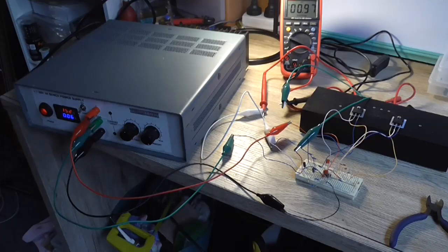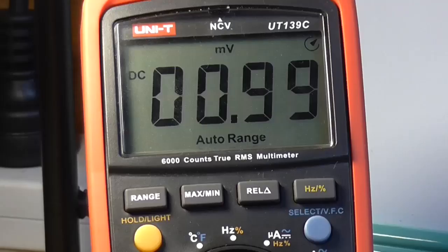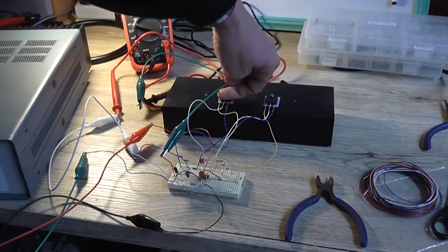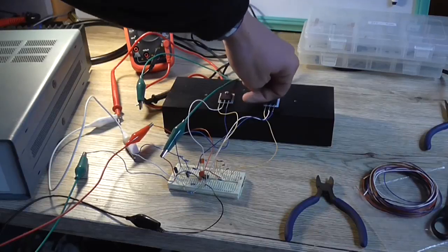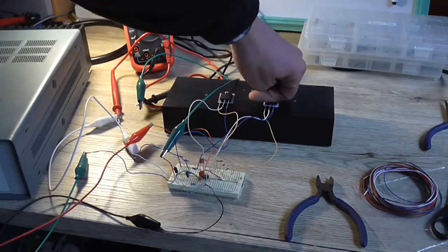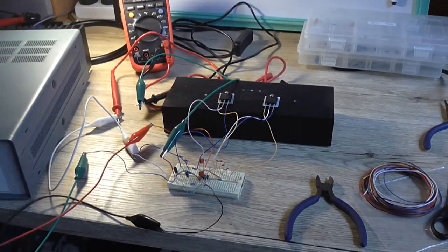and we're drawing currently 60 mA, and the DC offset is less than a millivolt. So I'm just going to check the output stage for unusual heating. There doesn't appear to be anything getting hot there. So now we need to put it into a dummy load and an oscilloscope. Turn that off for now. And we'll see what the output sine wave is.